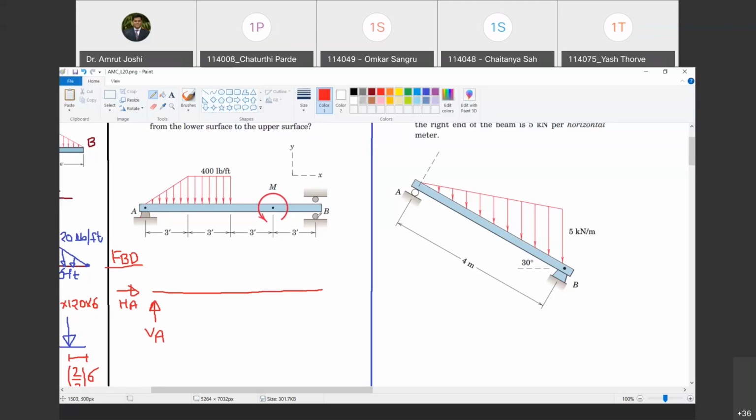But right now we will assume that only the roller below is in action. Are you with me? That means the beam is touching the lower surface. Yes. That's what we assume. That is our assumption. So in that case, what kind of reaction can be offered? Only upward reaction can be offered. Yes. So I assume that the lower roller is active.